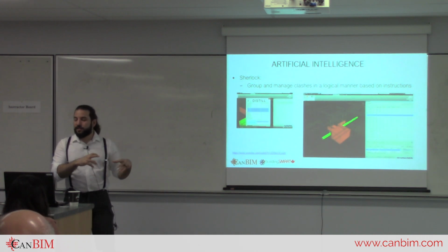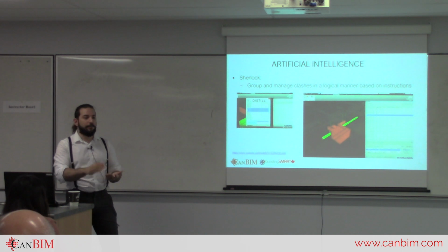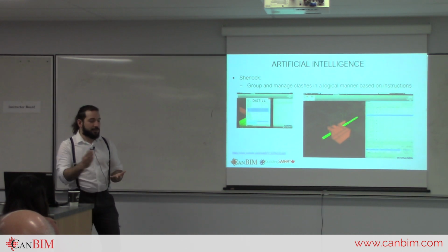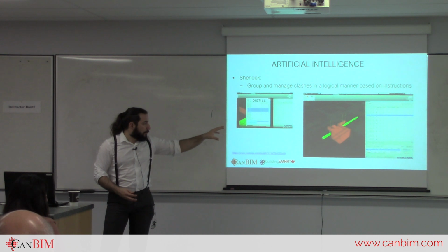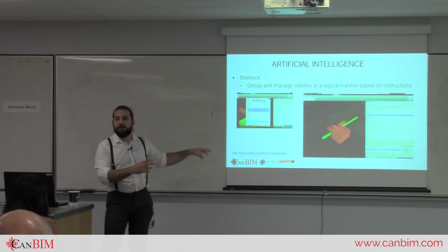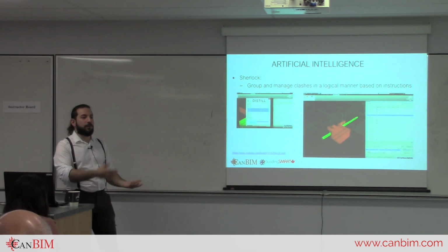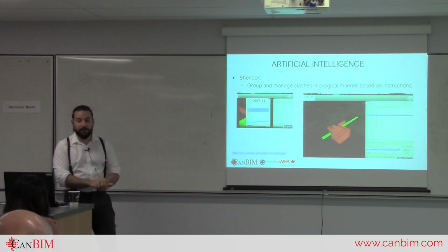Clash detection software tends to give you everything, like every single object running into another object. But if you think about it from a design perspective, I just need to maybe move one device from there and this problem will be solved. And that is what I want to see. I don't want to see 10 items for this single issue.